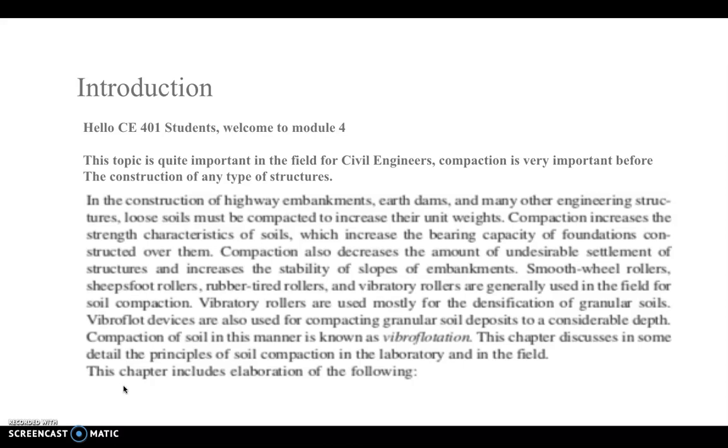When you compact the soil, of course, our soil contains air, so we try to compact that, and it generally decreases its compressibility and decreases its permeability, and it will reduce the voids ratio, making it more difficult for water to flow through soil.